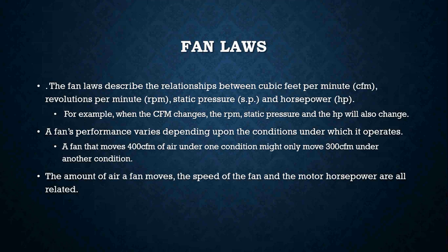It's going to affect the static pressure inside the ductwork. It's going to affect the horsepower of that motor. So again, it's back to like I said before: if a unit's fan isn't operating correctly, it's going to affect other areas of that unit's performance.